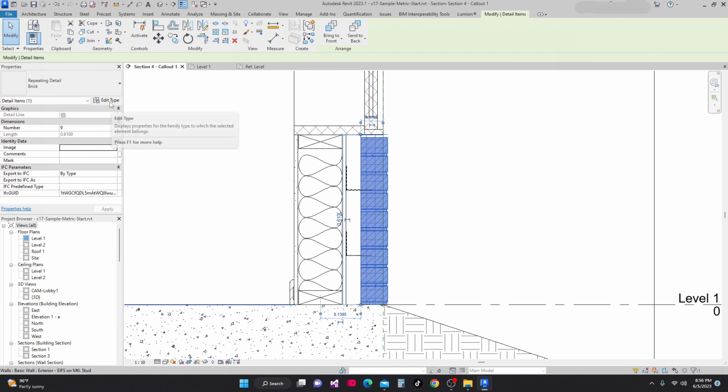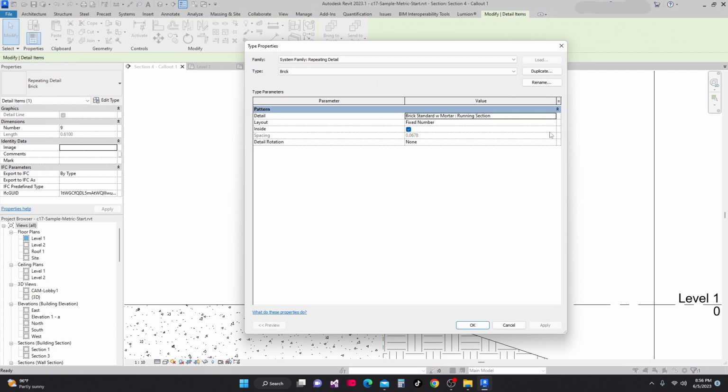And then again, there is also a fill available space. I go back to that one. There is a fill available space, meaning regardless of the value you choose for spacing, the detail component is repeated on the path using its actual width as the spacing value.